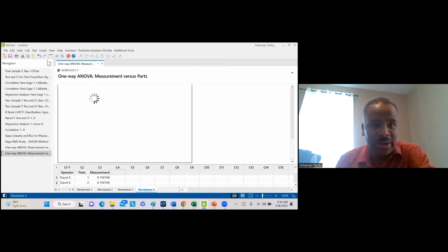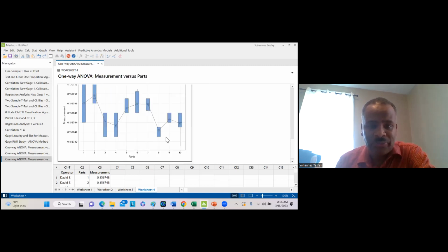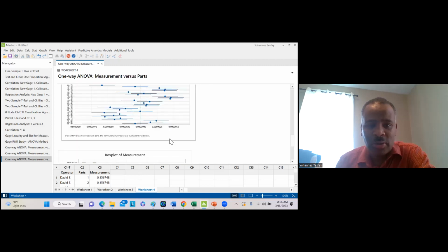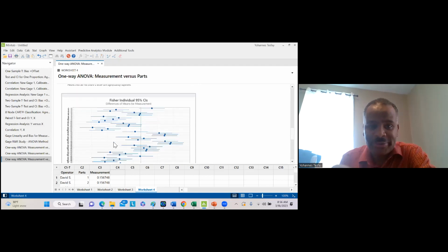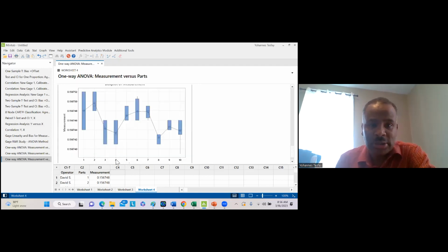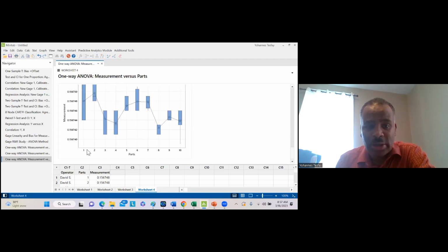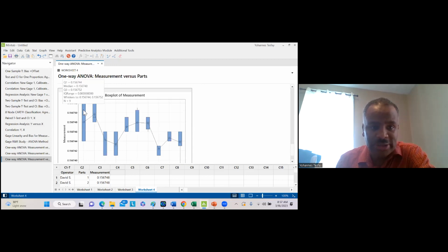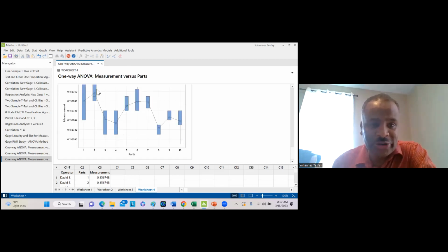Let's say, I'm gonna also just perform, okay, comparison. Feature. I'm gonna put that, and I'm gonna say okay. So this is all the comparison, one part to the other. They're trying to just measure, but as you see, part-to-part variation is significant. Okay, significant. So part one measured from here to here to here, the box, the variation. So that means there is error associated with the gauging system, repeatability. Part two is going to just measure like that.